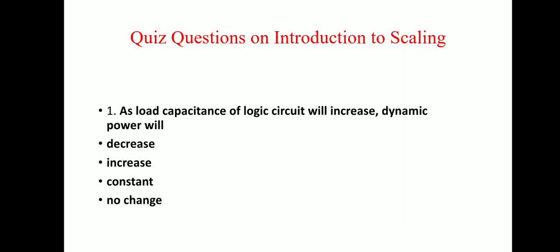Quiz questions on the introduction to scaling. First one: as the load capacitance of a logic circuit increases, will the dynamic power decrease, increase, stay constant, or show no change?